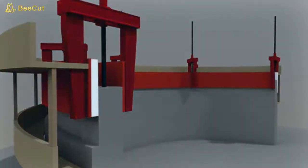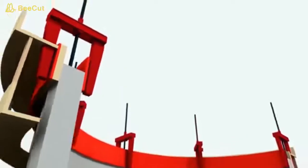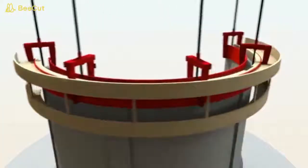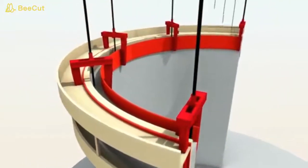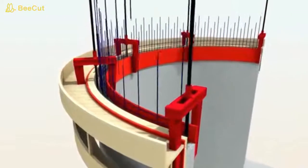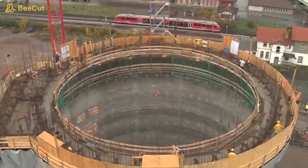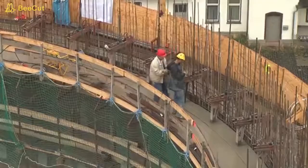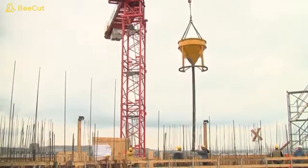To the yoke legs, walkaway brackets are connected. This walkaway bracket will enable proper placement of the concrete. The entire slip form assembly is lifted using strand rod and lifting jack. Such primary components are placed at equal intervals to achieve uniform and good weight distribution. Lifting is assisted in some constructions by the use of a hydraulic pump component.